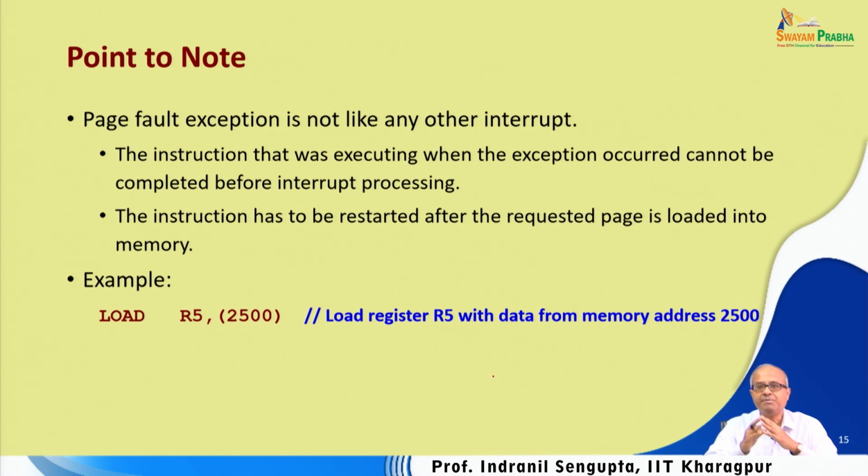Now, there is one very important point. Let us digress a little bit. In computer organization, I hope many of you have studied interrupts. I am talking of hardware interrupts. Every processor has an interrupt pin through which, whenever some external device sends an interrupt, the processor acknowledges the interrupt, control jumps to some interrupt handler or interrupt service routine, some routine is executed and control returns back to the program which was executing.